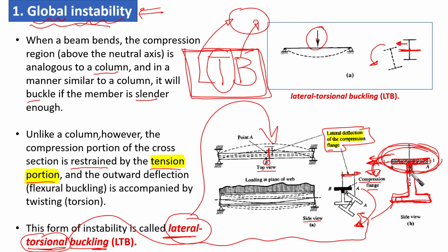it is going to restrain the bottom of the compression member or the compression part. Then this flange is going to be like this, as we said, it is going to move in this way. So the solid black part here is going to move in this way, laterally, and making this twisting motion. Okay, so this is the composition of these two parts, lateral buckling and torsion.